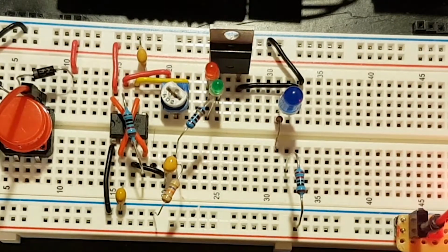This also means you can achieve far greater switching speeds and recovery. Recovery of the silicon diodes can range from several microseconds to a few nanoseconds, whereas the Schottky diodes are about 100 picoseconds, which is practically instant. The drawback of the increased conductivity means the reverse leakage current is higher.